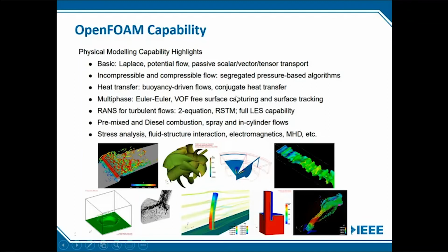So basically what people do is they don't just use OpenFOAM solvers as they are. These solvers already exist, and a user just has to come and hit run, but these solvers are there for a particular geometry, for a particular physics problem. These are all the basic physics problems. If you're doing analysis, your problem might be much more complex than the basic physics problem for which the solver is built. So what you do is you take this basic solver, make a copy of it, and then change the settings of these basic solvers to reflect the settings of your custom problem.